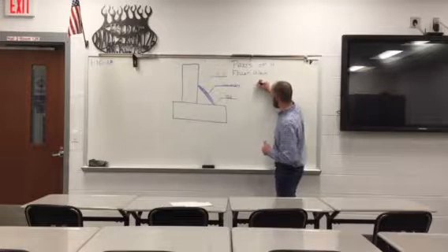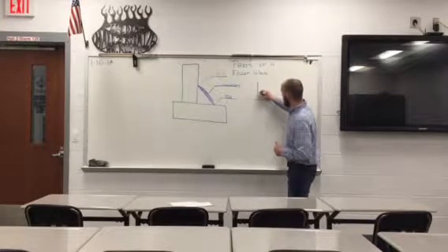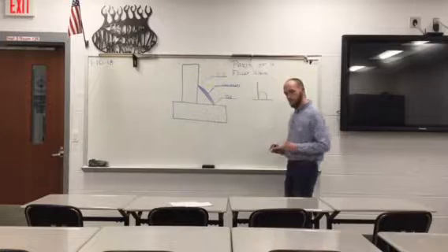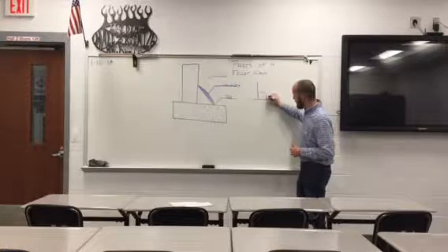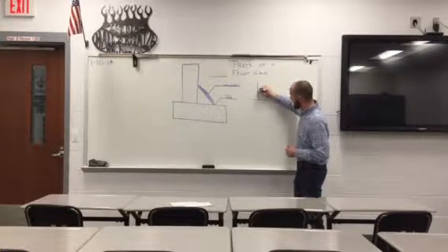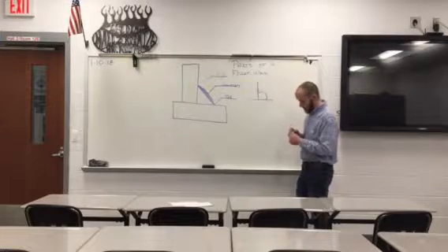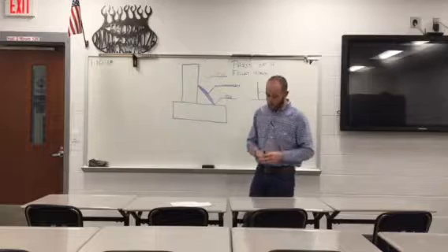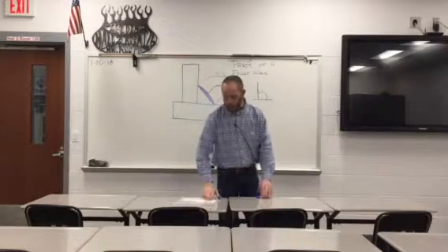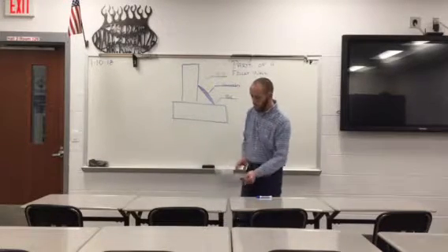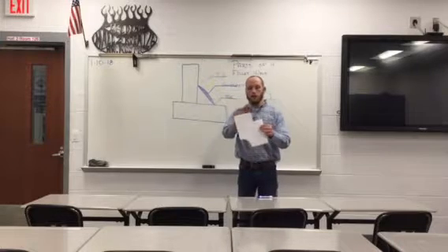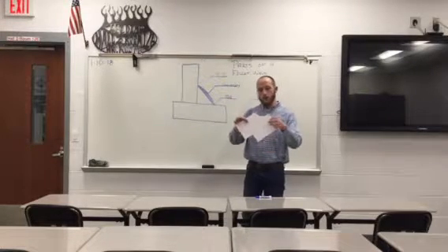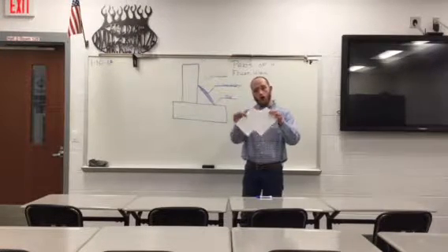Let's say we had this weld here, and we had excessive weld convexity. These are the sharp corners I'm talking about. That's a great spot for a crack or a tear to start. I'm going to demonstrate that using this piece of paper. I've got a nice square edge on this corner and a nice radiused wet end look, we'll call it, on this corner.